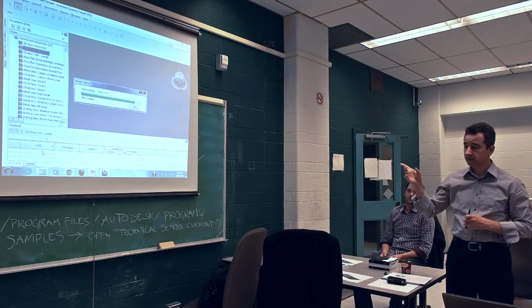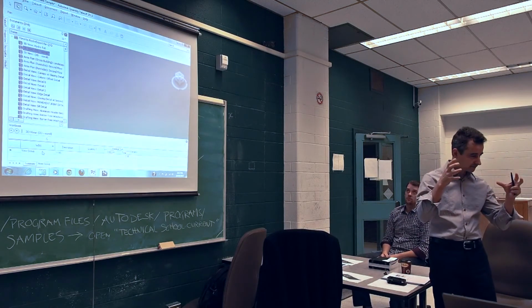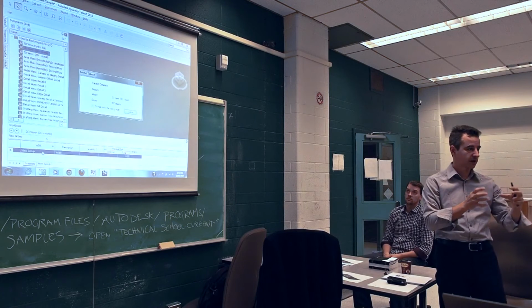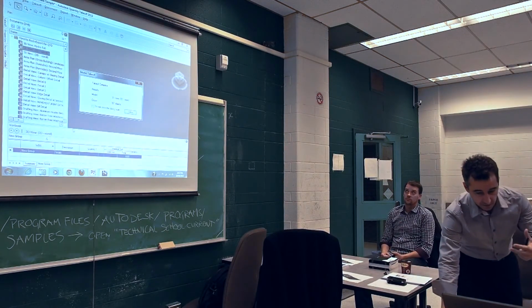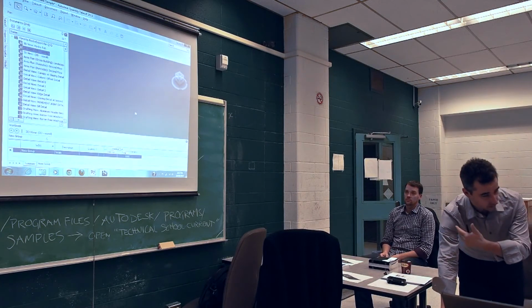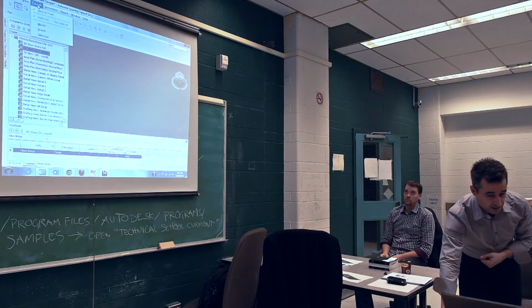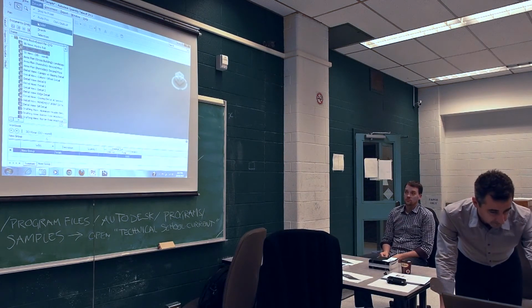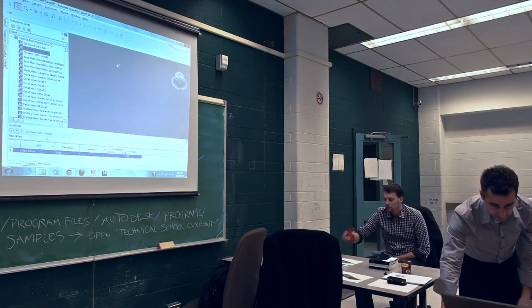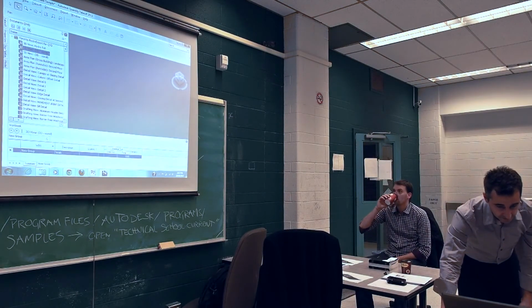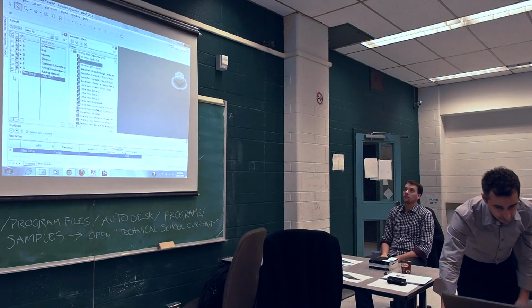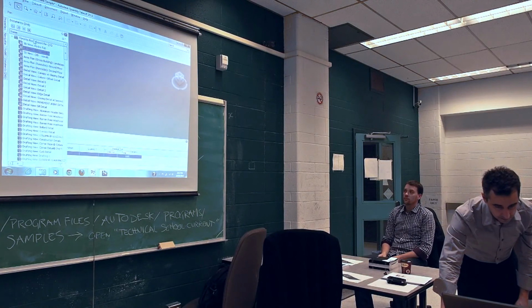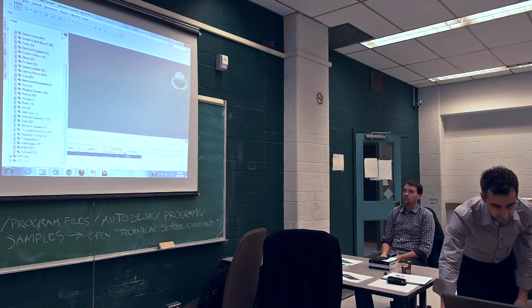But at the end of this, you can take off groups of elements, just one or the entire building. I selected the walls because we've seen the walls before, but you can take off the entire model right here. That's going to take a little while, and let's see what the takeoff resulted in. So I have these walls, takeoff.